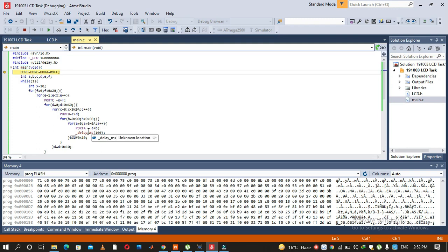Once the bit A reaches 10, it displays the number at port A, and then the for loop of A closes, and the for loop of B starts from the beginning. B at the beginning is 0x00, and it has to go to 0x60, and each value of B is added into A to give out the sum in the BCD LED 7 segment digits.